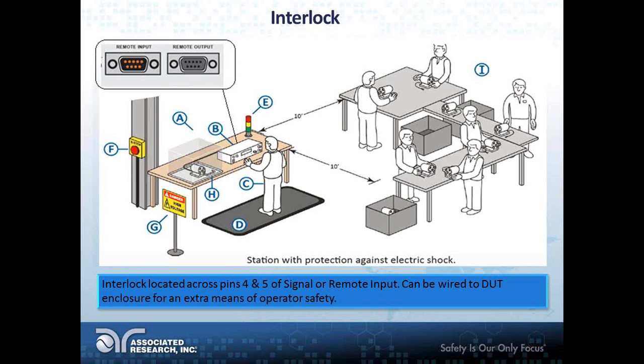it can be wired to a DUT enclosure. For a safe workstation, you want to keep your device under test inside a safety enclosure to prevent any accidents or anybody coming in contact with your product under test, because it's charged up during a Hipot test, and touching it can cause an electrical shock to whoever comes in contact with it.